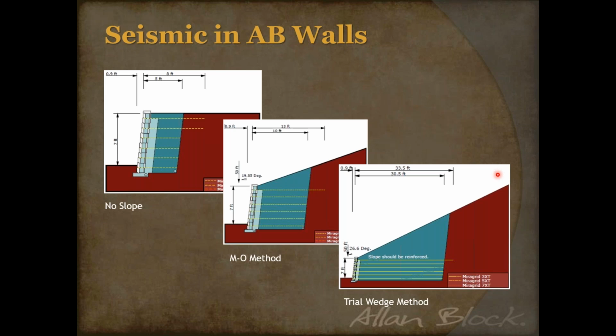What seismic acceleration was the analysis based on in the wall comparison? So this was at 0.4. This would have been the example that we had way back in the first part of this presentation. So yeah, we used just 0.4 g as kind of the control on this one. Soils were just our default value at 30 degrees. So kind of giving you a little background on that. Probably should put that on the screen so you can get that. But yeah, these are just screenshots from our software in support of the talking point. So great question here.